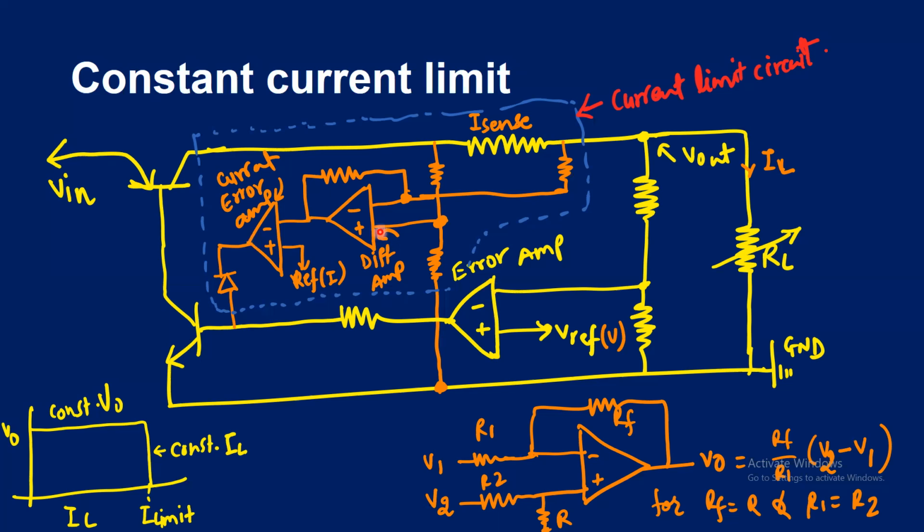So now what we see here is, as long as the load current is below the limit threshold, the output of the current error amplifier is high. So the logic 1 comes here, for example, and the voltage error amplifier right here in the bottom in yellow keeps the regulator in the constant voltage mode. So our regulator is working fine, and the output here is high.